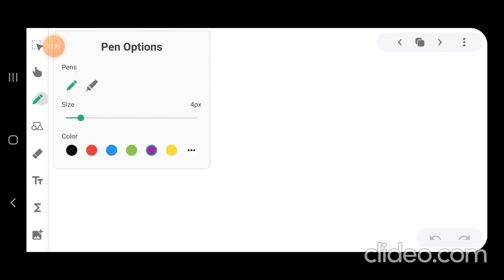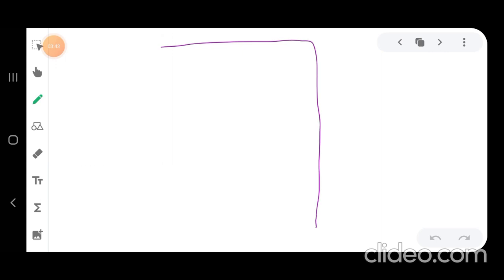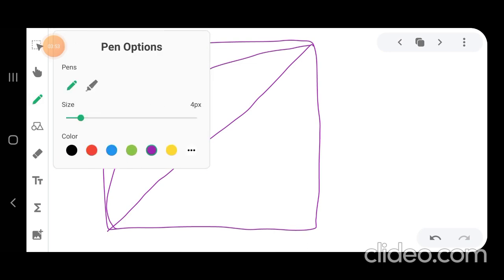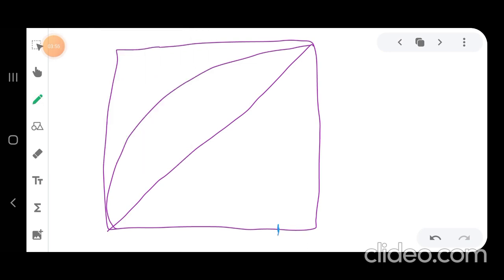Again, you need to draw using the McCabe-Thiele diagram. Suppose this is your graph paper, this is your 45-degree line, and this is your equilibrium curve. So this is x and this is y. You specify where your xd is, here for example, and it's constant. We have variable R, and we are in the case of constant xd, so the slope will be variable.